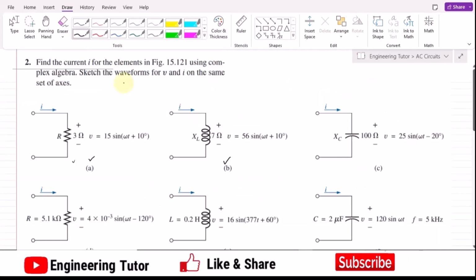Welcome back, guys. Again, question number 2, and today we are going to solve part C of it. Recently we have covered all the basic steps when the impedance solely consisted of a resistive element, and in part B the impedance was basically the inductive reactance. Today in part C we have the capacitive reactance, which has the value of 100 ohm, and the voltage developed across it is 25 sine of omega t minus 20 degrees.